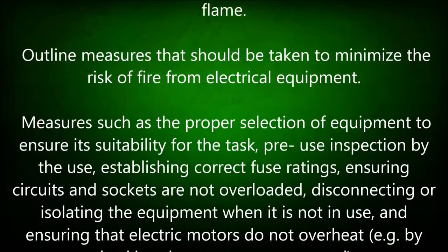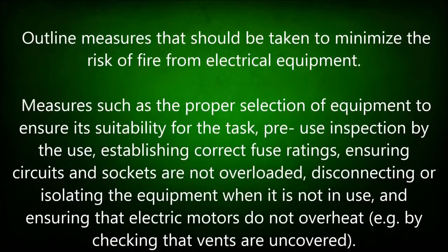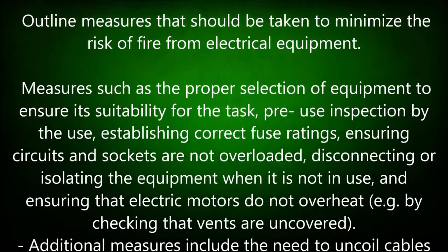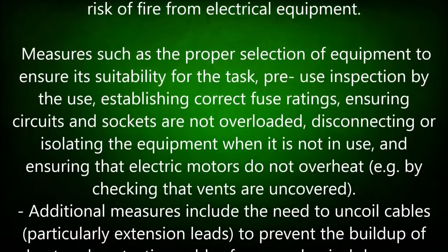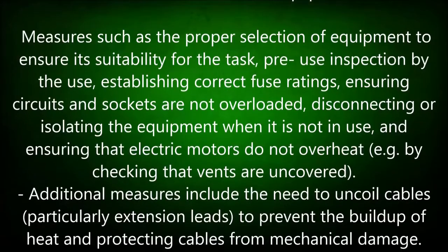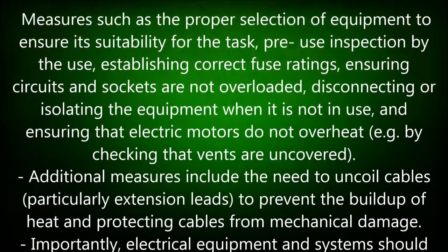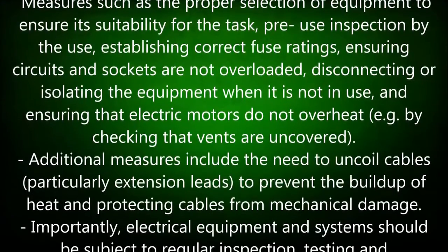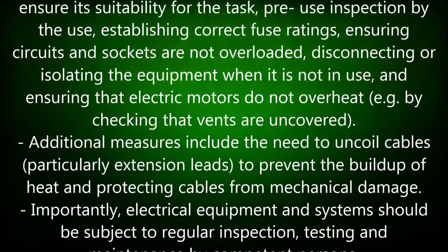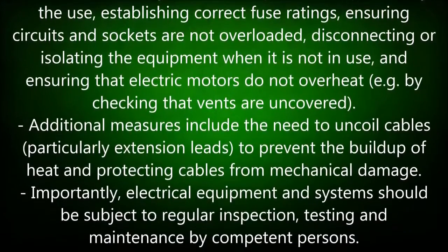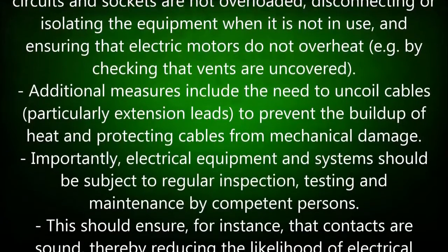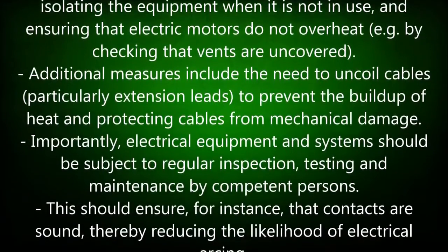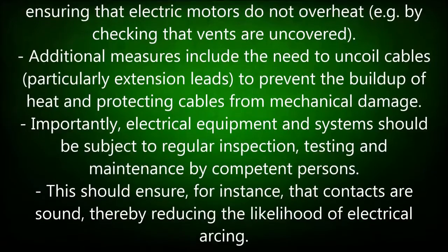Additional measures include the need to uncoil cables, particularly extension leads, to prevent the buildup of heat and protecting cables from mechanical damage. Importantly, electrical equipment and systems should be subject to regular inspection, testing and maintenance by competent persons. This should ensure, for instance, that contacts are sound, thereby reducing the likelihood of electrical arcing.